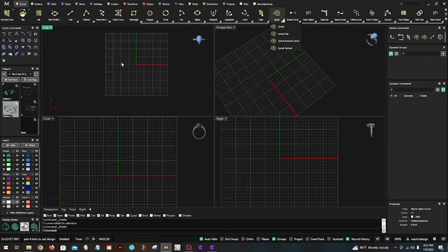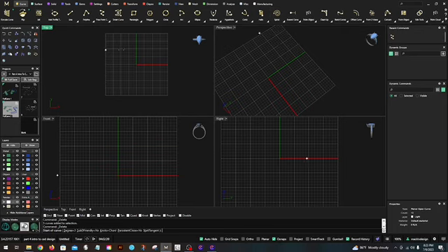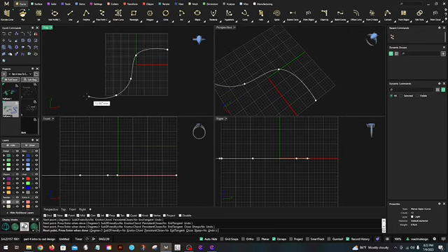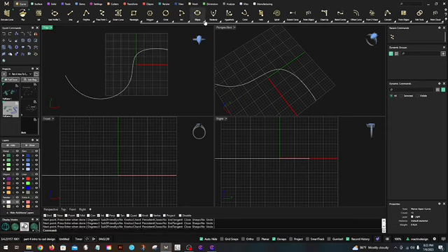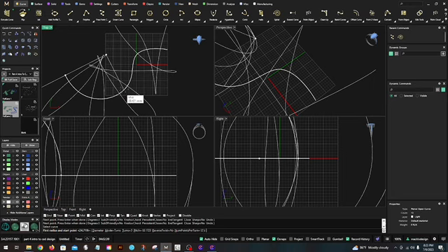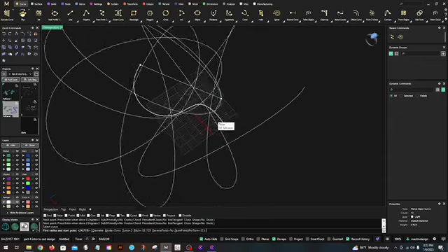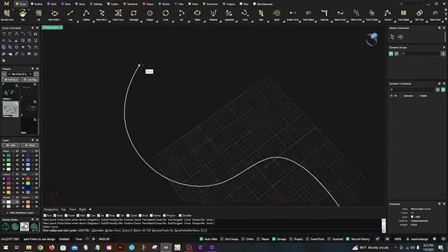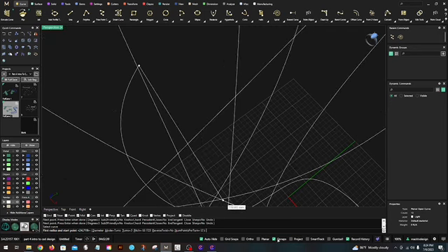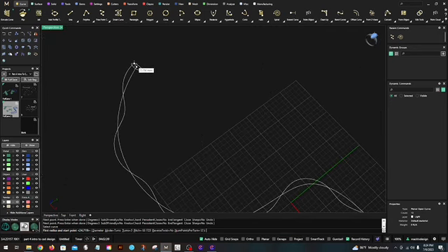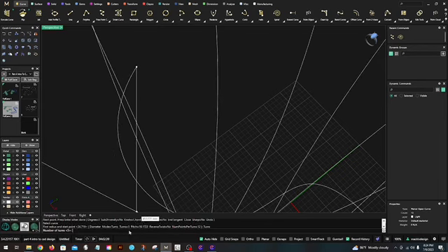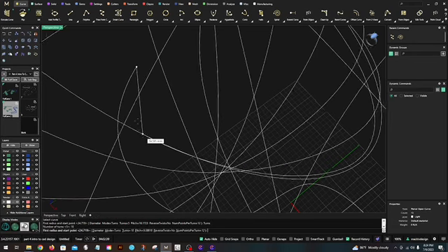All right, spiral around a curve. So let's go back and do our freeform curve and see what happens when we do spiral around a curve. I'm looking at my command line. It says select curve. And wowzy zowzy. I think it's out of control. There we go. So you want to just get really close, and you probably want to make sure your O-snaps are off because it's going to go crazy. All right, and it does tell you how many turns, so I'm going to do 10.